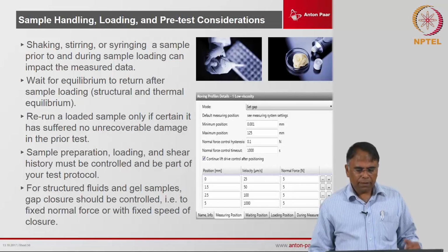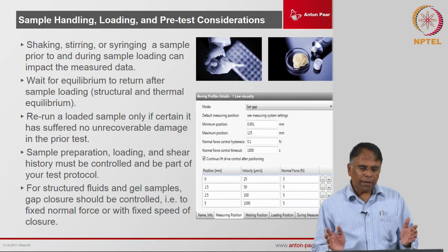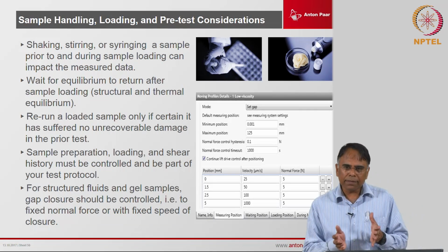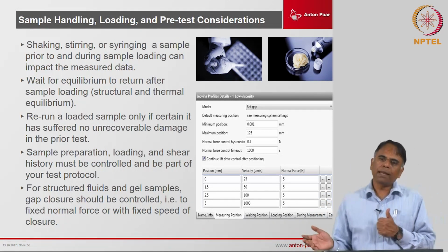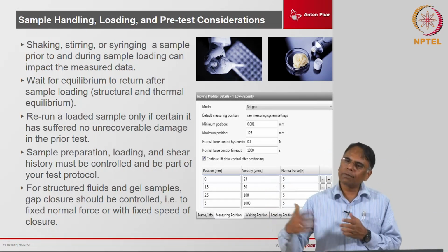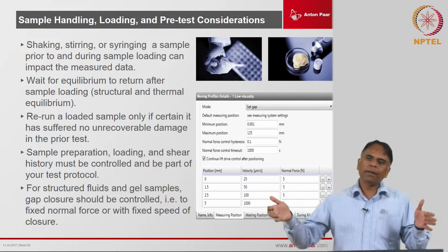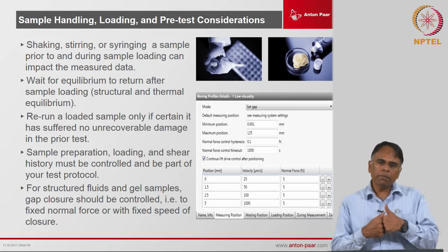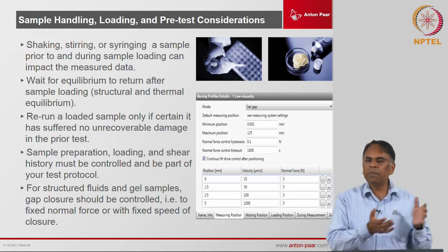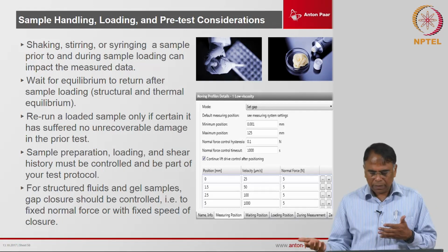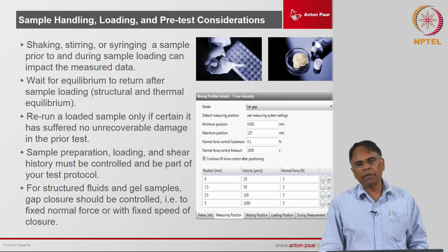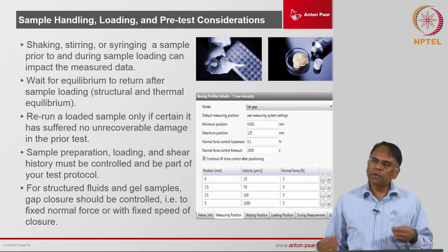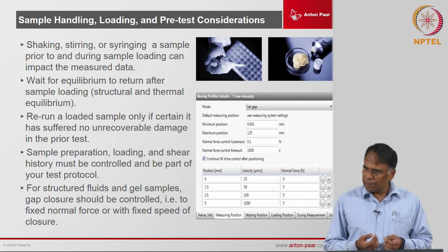So, always, once we have taken care of the right geometry for the right samples and the right testing parameters, and also understood what is really happening in the test, looking at the torque and setting the right parameters to get the torque in the proper range, at the same time you should also take care of the basic sample preparation. When you are loading the sample, especially viscoelastic liquid samples, make sure that there are no micro bubbles in the sample.